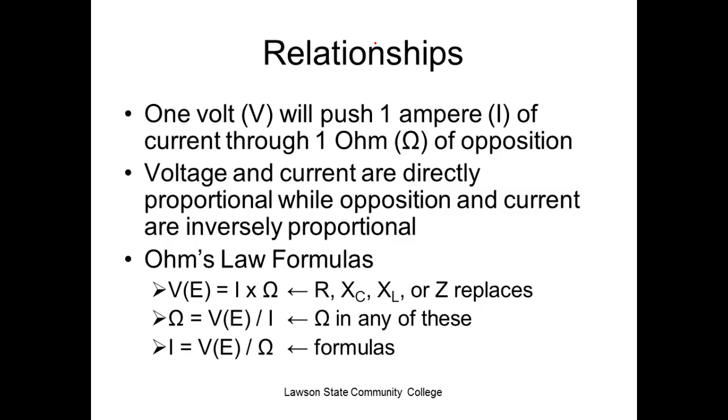Well, this is where your inductors and your capacitors come into play. We can set up what we call tuned circuits, which allow a carrier to come through and block all the other carriers. So you can look on your radio when you tune 93.7, it says 93.7 megahertz, right? Well, that's the carrier frequency.